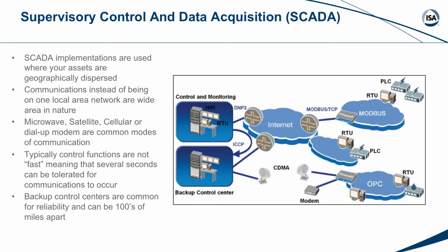SCADA, or SCADA, if you're from down under, supervisory control and data acquisition. So the best way to think about this type of implementation is that the distributed control system and programmable logic controller are inside the fence. You have a chain link fence around a factory or around a pumping installation, and most of that control is inside the fence. SCADA is outside of the fence, or many miles between the fences.